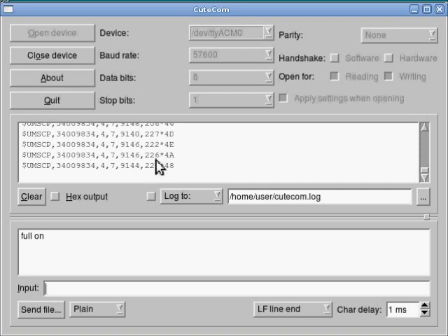This last, as I said, is signal strength. This is a logarithmic scale. It ranges from about 90 or so on the low side, low signal, to about 230, maybe 240 for a really strong signal right next to the receiver. And this is not in decibels. It's essentially an arbitrary scale, but it is logarithmic in nature. And noise floor can range from about 90 to about 130 or so on this scale.